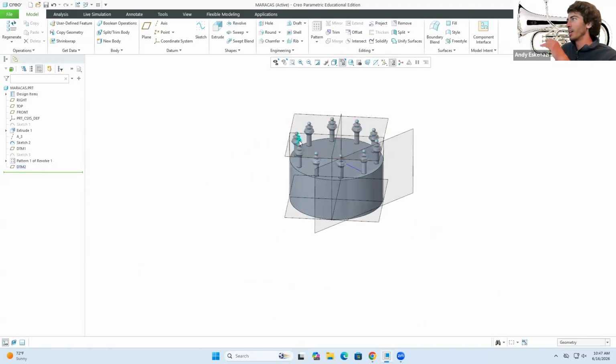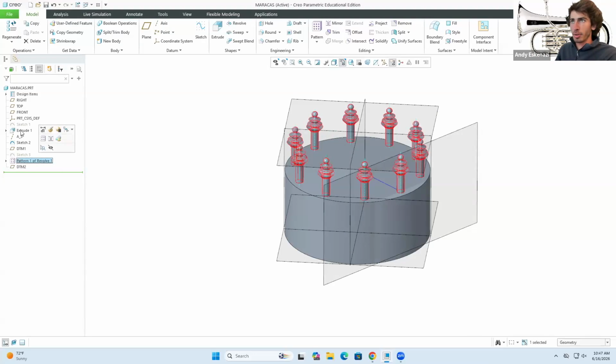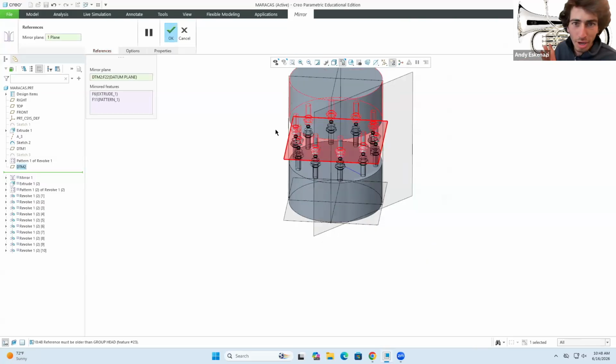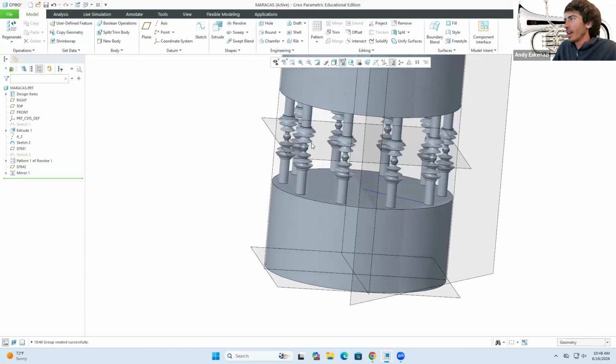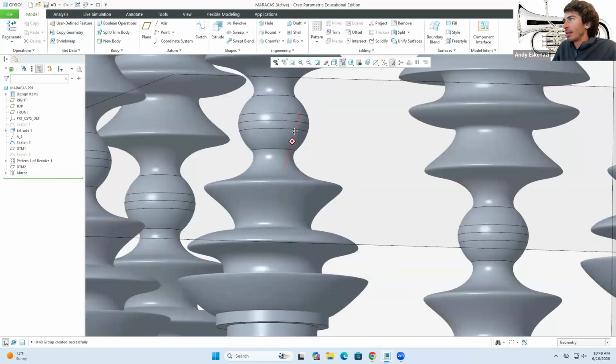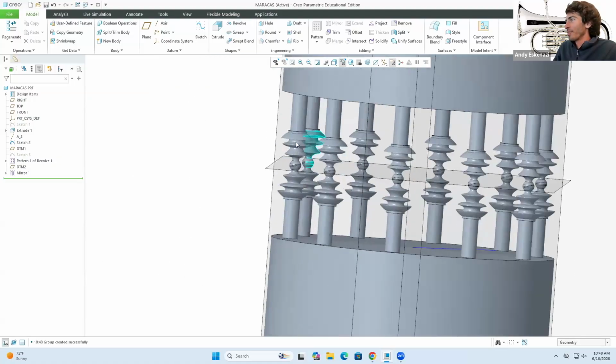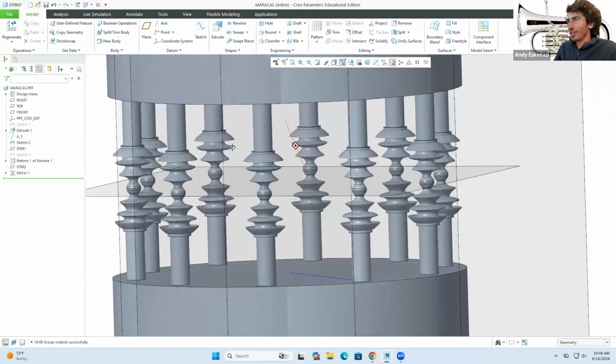It's gonna be interesting. So now I'll click on my pattern and I'll click on my extrude. And you see that again, all of these areas unlocked. So I'll go here to set mirror. I'm gonna say, right, mirror plane, that in here. So this is gonna look very weird, but again, it's telling you how powerful all of these things are. And I'll go here to OK. And what do you get? Something that is kind of cool. These are interesting looking columns that you get in there.